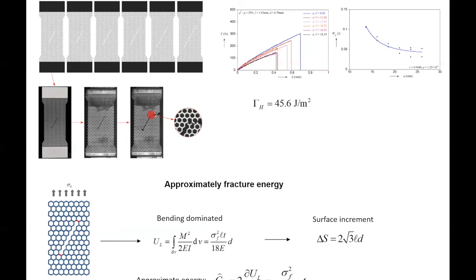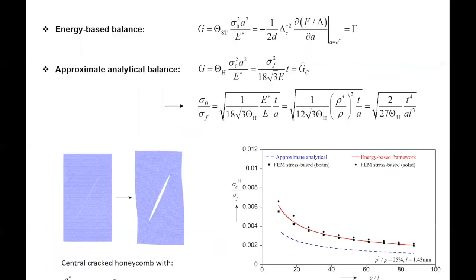And then we did the same approximate simple analytical calculation. If you remove the elastic energy of one strut right before failure, and you think about the extension of the crack, how much approximate critical energy release do you get? And then we put all of this together again. And now, as you can see, deviations will start to happen, right? Your formula is much, much cruder. Well, in this case, the strength, the stress criterion, finite elements, and the fracture one are kind of close too.